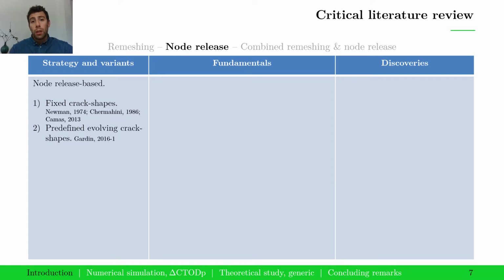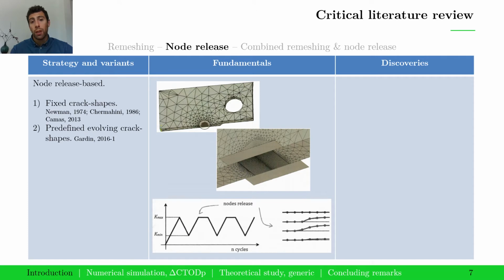There are other strategies based on node release. Here the crack shape can be either fixed or the mesh can be arranged in such a way that by releasing nodes, the crack evolves in a predefined fashion. These strategies are based on a 3-dimensional elastic-plastic finite element model of the cracked body with a rigid surface on the fracture plane to simulate PICC while we apply load cycles.